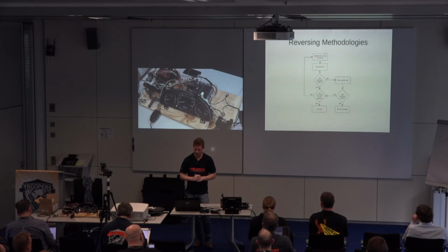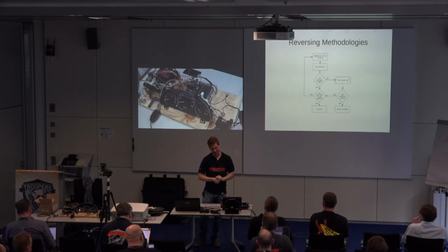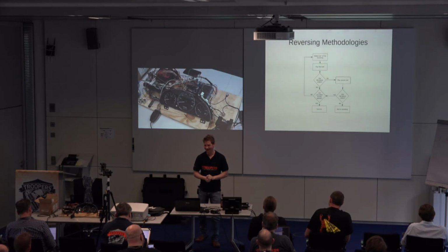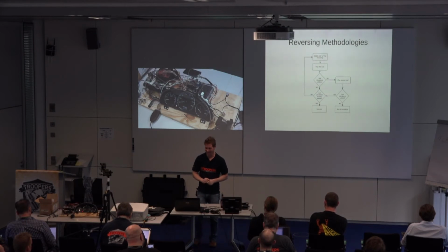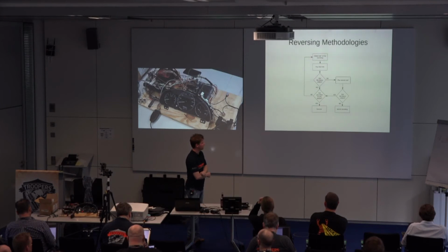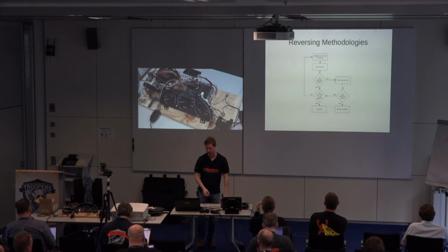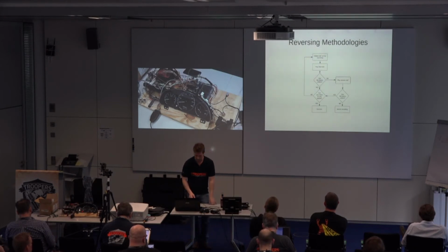I have seen it get a little worse on occasion. The worst case, you have to disconnect the battery. That's happened on just a couple occasions. One time the car actually wouldn't turn off even with the keys in my hand. That was a little scary. But again, it was just disconnecting the battery. And you may have to pull some fuses too, just because there's some capacitive stuff. But for the most part, this will work.